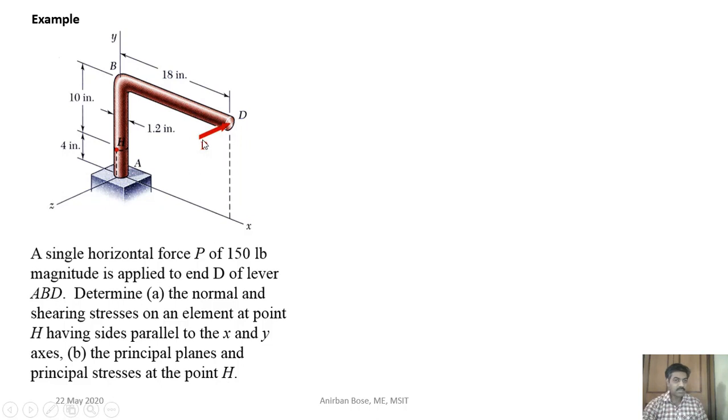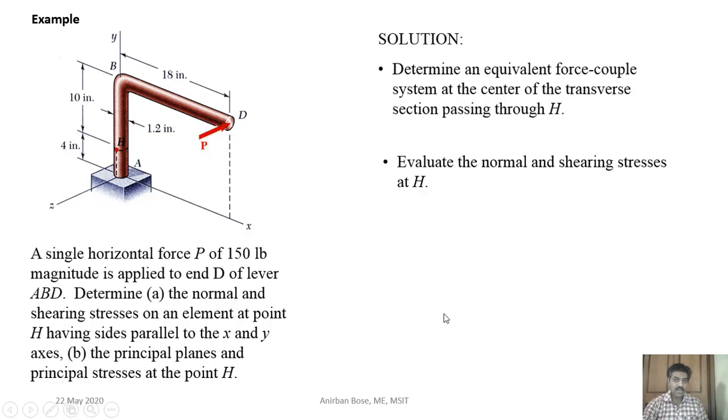So here the problem starts from the loading that we discussed in the last class. From the loading, first we have to calculate the stress element. From the stress element we have to calculate the principal stresses. Okay, so let us see how we can do that. So first tell me what kind of loading will come. Because of this, definitely there will be a twisting about the y-axis, so a torsion will come, and because of pure torsion, shear will come.